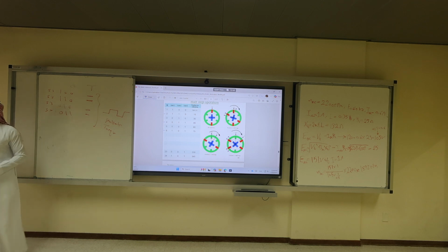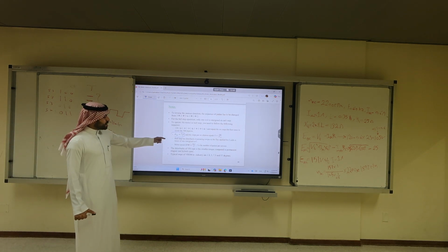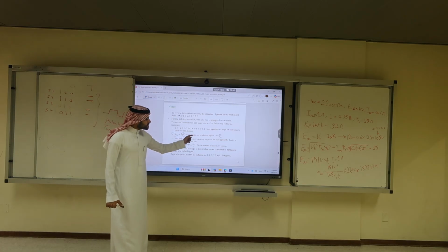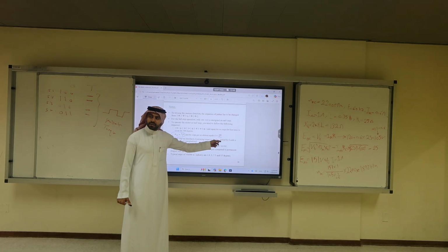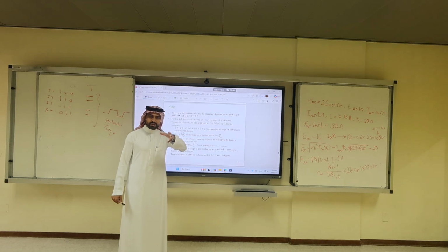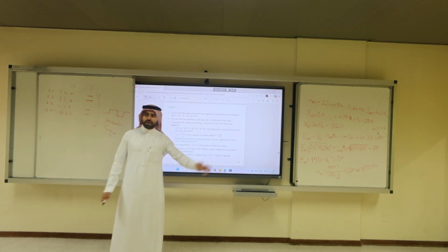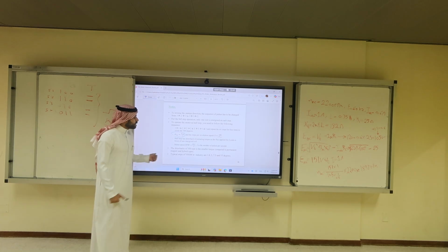Is it clear? Yes. Another thing we want to discuss is the steps per revolution, which is equal to 360 over the angle. Basically 360 over 60, how many steps do you have? 360 over 30? 6 steps. Over 15? 12 steps. So sometimes people call it 12-step operation, the 6-step operation. That's it.